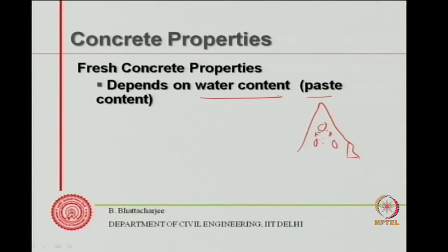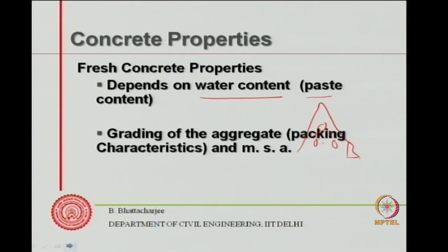Therefore, in concrete, setting properties of concrete are governed by properties of both cement as well as the properties of admixtures they control. So it should remain plastic up to the compaction stage, complete molding stage actually, up to complete molding stage, all right, and it should be easily flowable. Now these properties are dictated by paste content and water content, mainly water content and paste content, right?